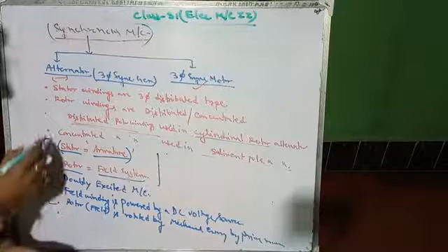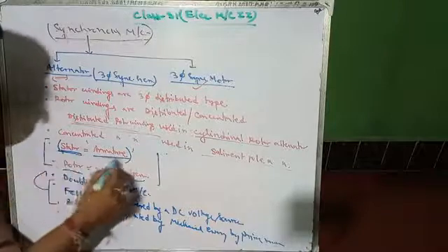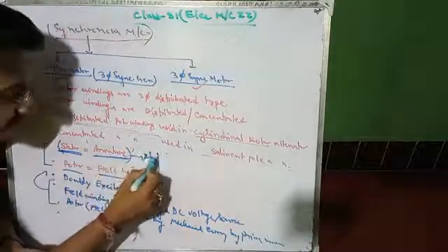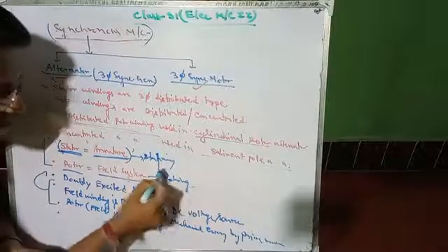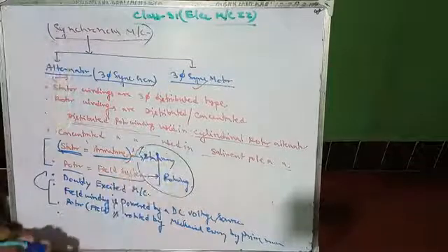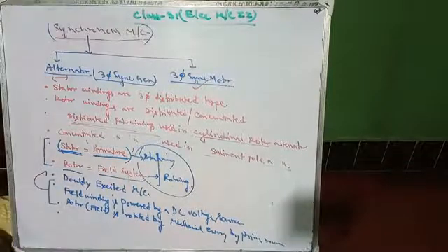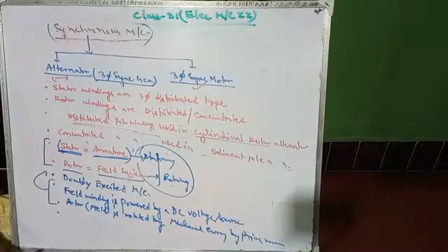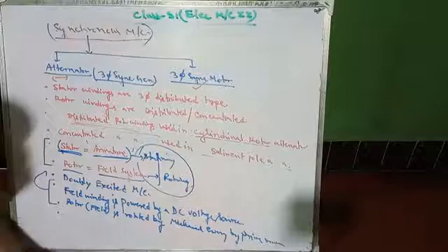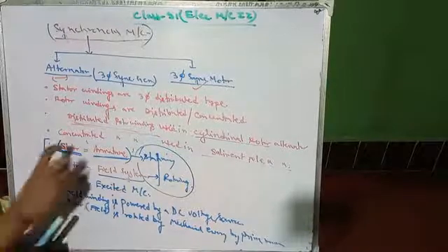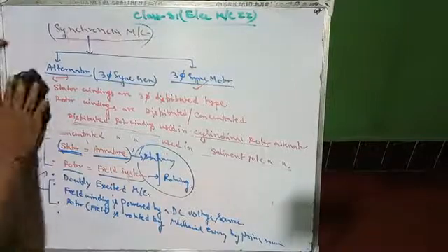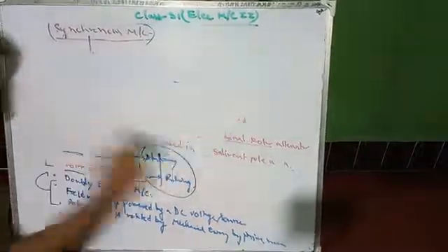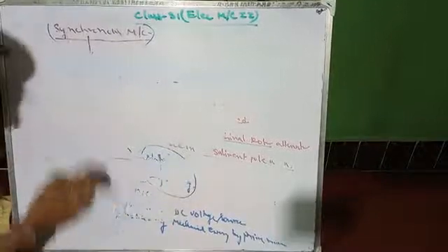But here, as I have discussed, the stator is called the armature, so the armature is stationary and the field system is rotating. This arrangement gives an advantage in the synchronous machine. So you have to understand this concept: why the armature is taken as stator and the field system is taken as rotor. This is also a basic for the alternator.